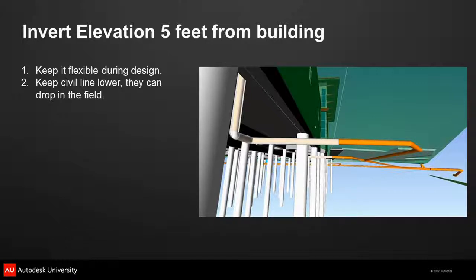It's typically more economical for the plumbing to go below the concrete beams than through them, unless you've got hill conditions. But most general contractors would prefer the plumbing not to be sleeved through the rebar. Are there any GCs in the room? Is that a fair assessment? That's my perspective from my structural background. Joseph Powell's not here with me; we have dialogues about it. He's the mechanical engineering background. It's just easier that way, but you're also increasing the amount of excavation the lower that line goes.